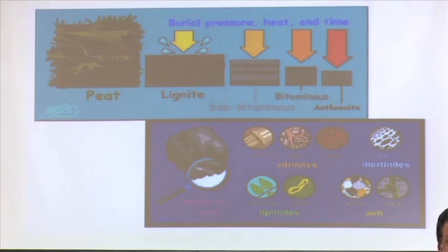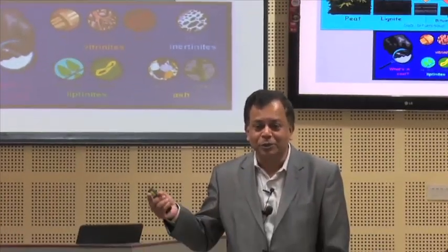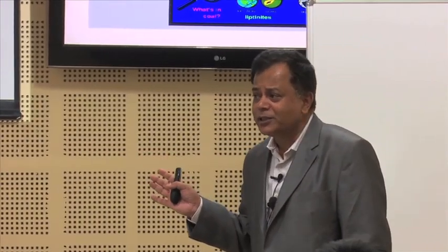That may not be 100% mineral matter. Suppose I say 40% ash, but if I have calcium carbonate in my coal, when I heat the coal the calcium carbonate can dissociate into CaO plus CO2, so the CO2 may go out, and my percentage could be different. But we get a guesstimate, a rough estimate, of the mineral matter contained in that coal. That is why we take ash, because it is very simple to determine the ash content of the coal.